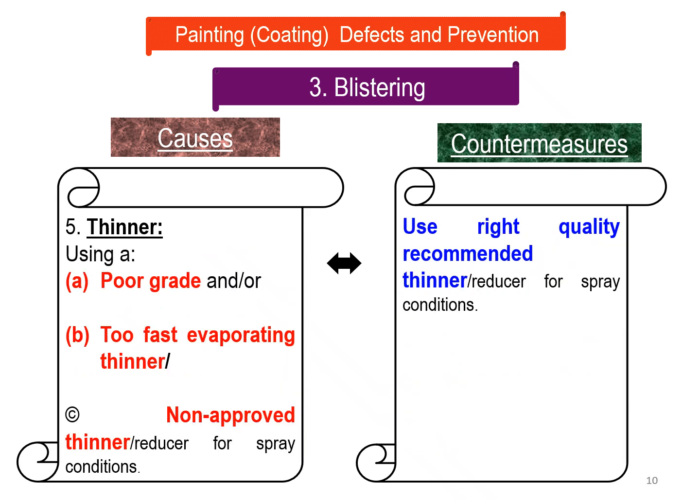Under the subject of blistering, the causes related to thinner could be using a poor grade thinner, or too fast evaporating thinner, or non-approved thinner. The recommendation is use the right quality recommended thinner.